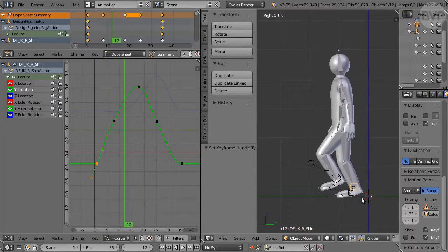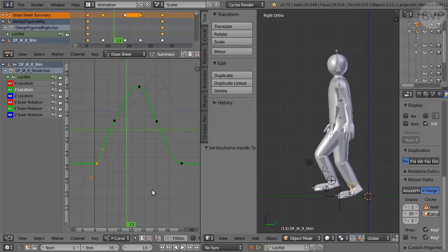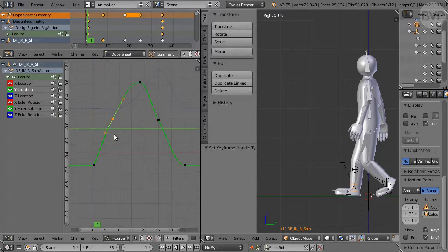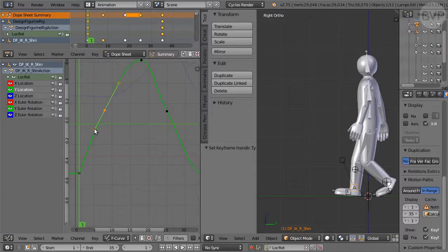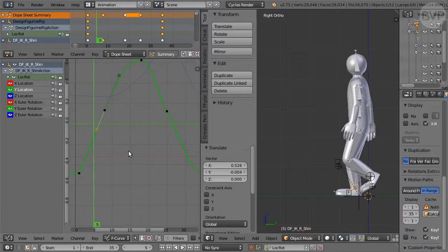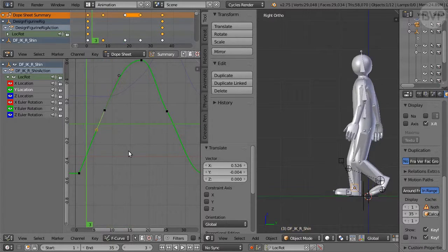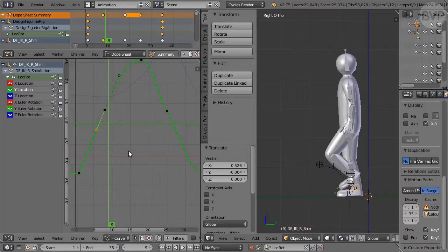Some backslide toward the next keyframe, and it seems to continue after it as well. Select the second keyframe, then drag the lower handle toward the curve to flatten the line. It's better but not completely solved. That can only mean that the rig object is moving too slowly.